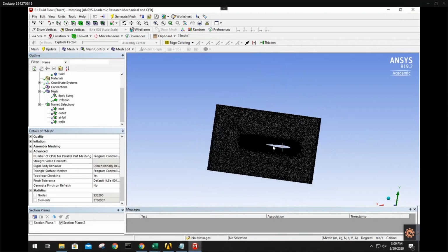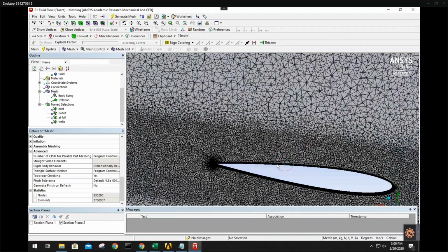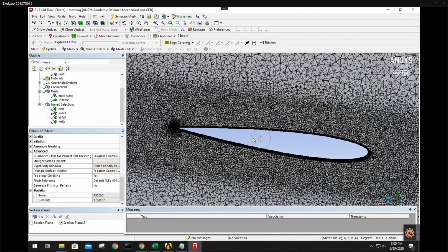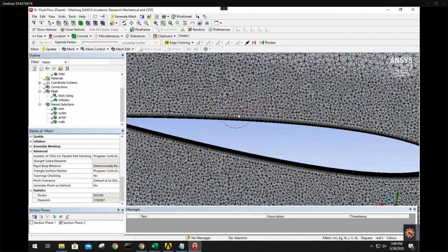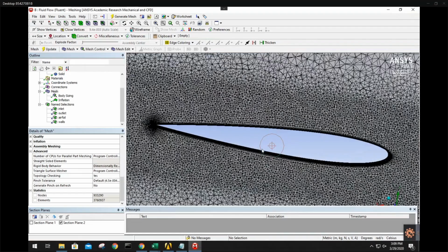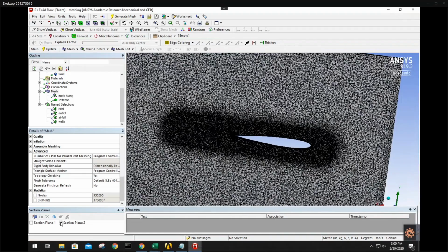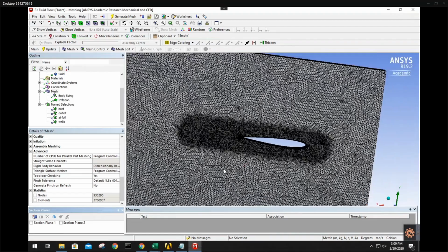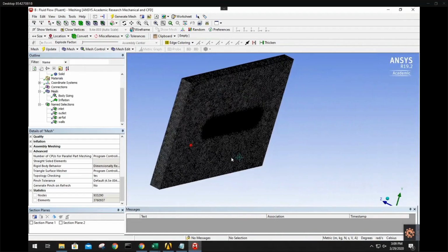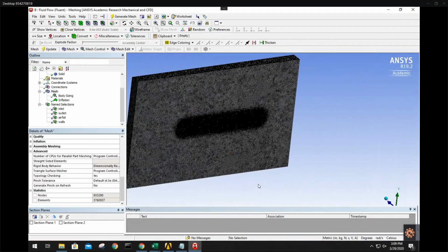And so here you can make sure that, even halfway through in the 3D mesh, it looks generally right, the inflation layer is proper. All of this weird mumbo jumbo, no idea why that happens, but I think it's because you're taking some 3D slice. So when I unclick that, boom, I see the edge again. So I think this looks generally ready to go.